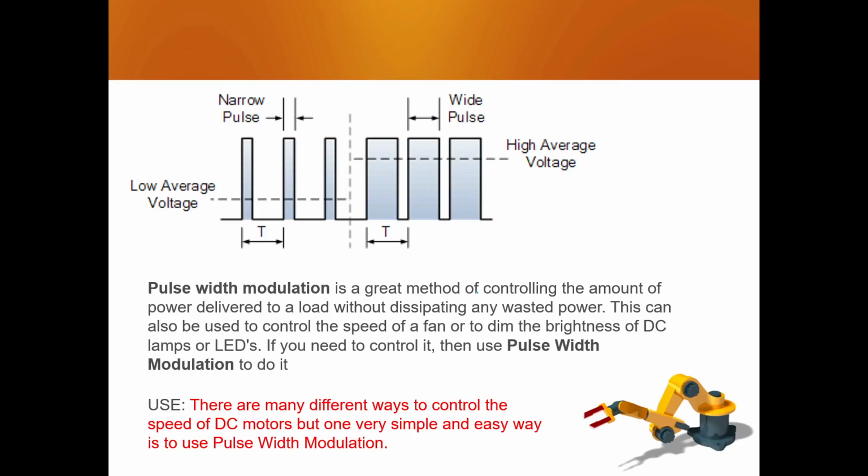Now, as I said, the thickness is what we call width. Here you see I have written the width of the pulse. You see this number one and number two. If you compare, number one is narrower and number two is wider. And this dotted line at the bottom is the average of this. If the width of the signal is higher, the average will be higher, and if the width is lesser, the average will be lesser.